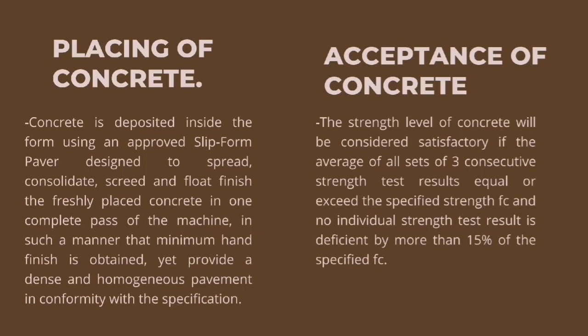Acceptance of concrete. The strength level of concrete will be considered satisfactory if the average of all sets of 3 consecutive strength test results is equal to or exceeds the specified strength, and no individual strength test result is deficient by more than 15% of the specified.